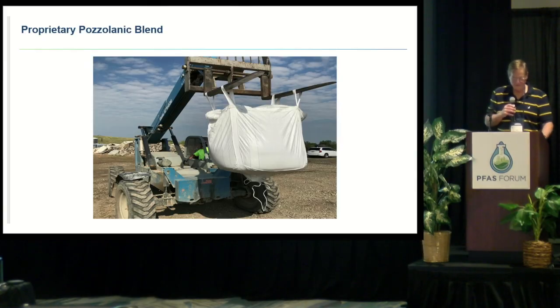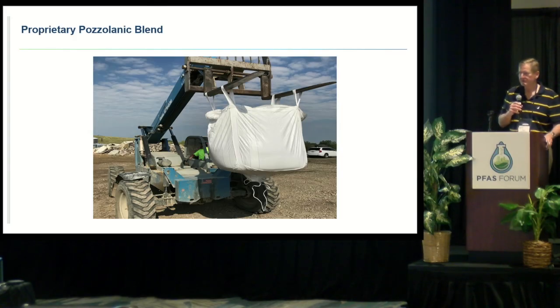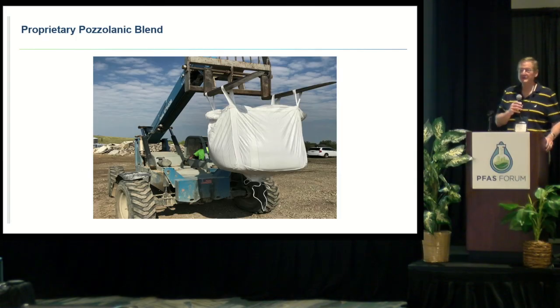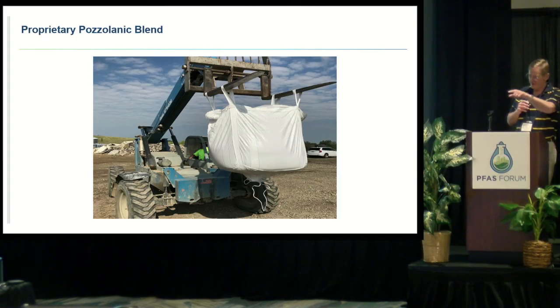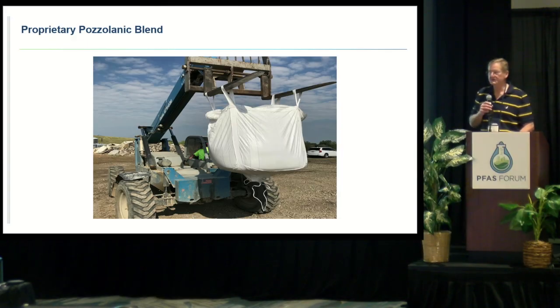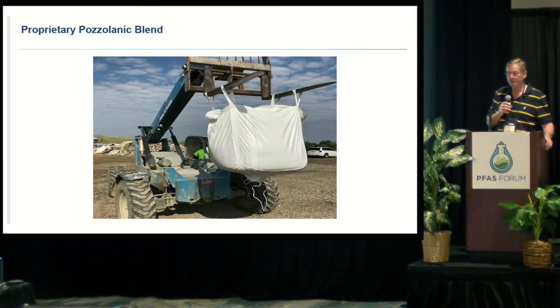What I'm going to describe is, please don't blame me for this name, but it was used for environmental purposes and it sets up. My former employer decided that they loved the name EnviroSet. It's got to be Enviro something in our business, right? So this is EnviroSet. I will say right off the bat that the sack there of EnviroSet is a proprietary pozzolanic blend, which just means it's cement-based, but it's not pure cement. I found by trial and error that straight cement wasn't the best way to go, so I blended other goodies into it that the cement plants would have.